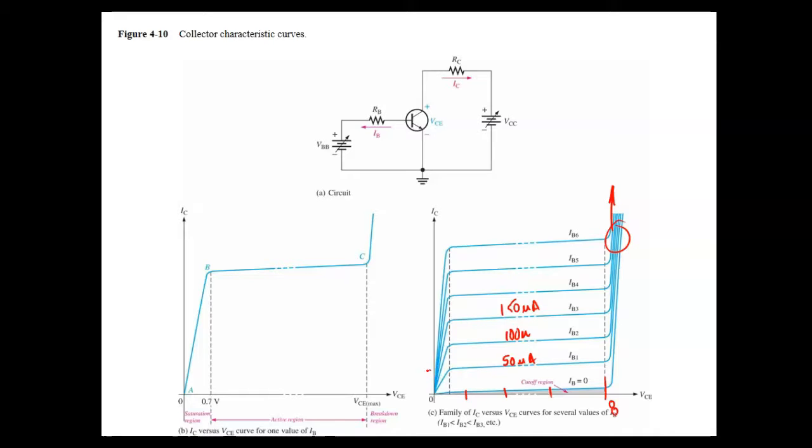Yeah, so we're probably going to set this off in microamps, maybe 50 like this, maybe 25, I don't know. And then if this was 50 microamps, then my first spot would be right there. And the next one would be right here. But what you see on the next one, it slants up just a little bit. And then when we went to 8 volts, it took off. And these are called characteristics curves. So basically we're trying to show that when we set a certain base current, the collector current doesn't change hardly anything for a base current. So what we're doing is basically proving beta.